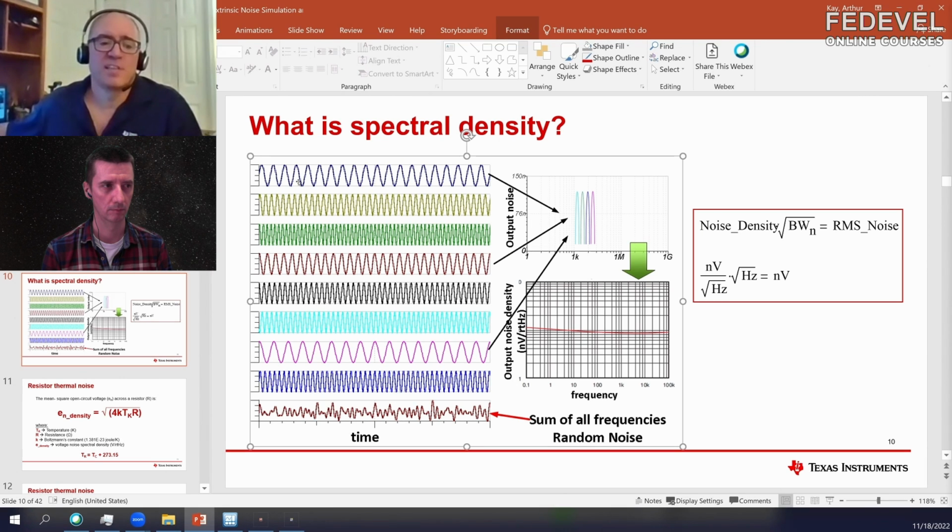If you take a sine wave at all these different frequencies and equal amplitude, you add them together, you're going to get a random signal. That's why we have this spectral density that's flat and basically represents the noise. The more of this that you can filter out, the lower your overall noise will be. Actually calculating using this curve is a little complicated, and we could go through the details on a separate session.